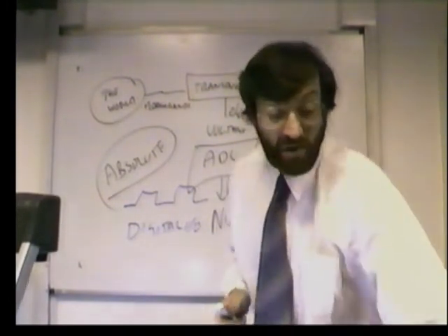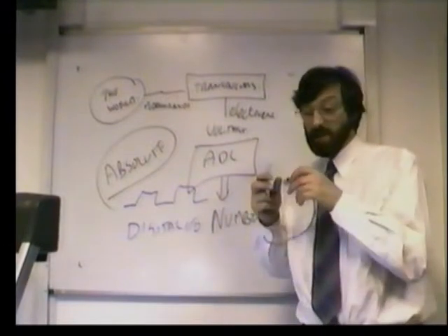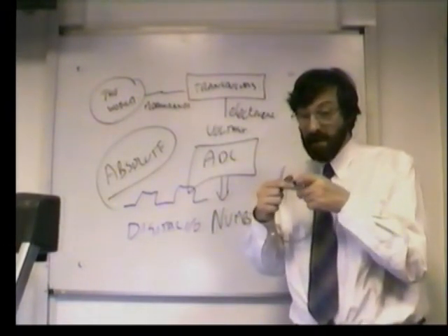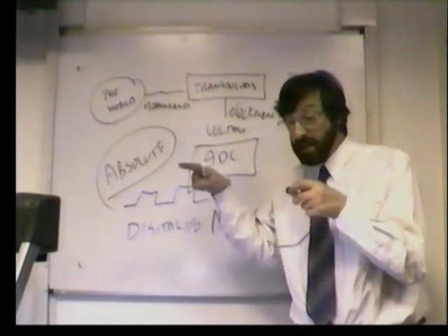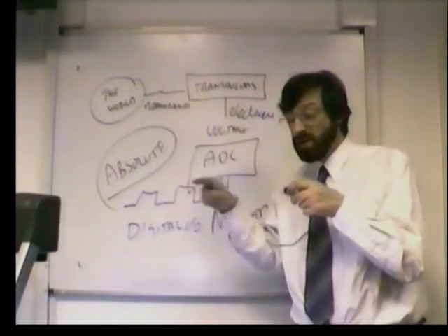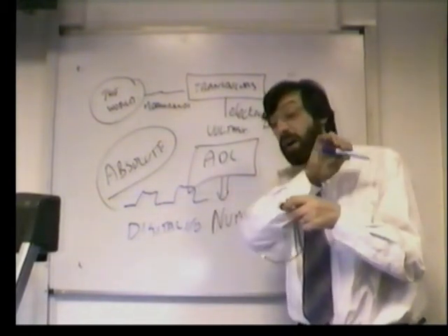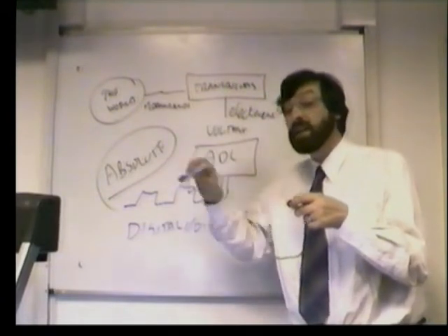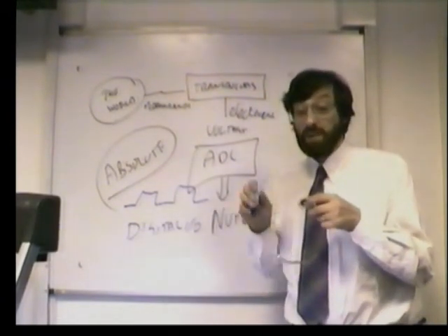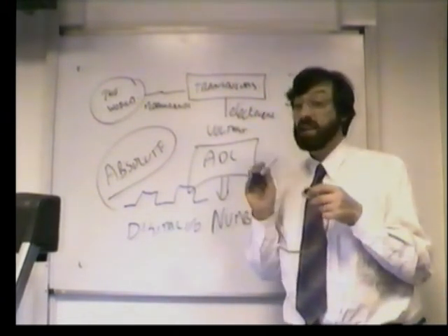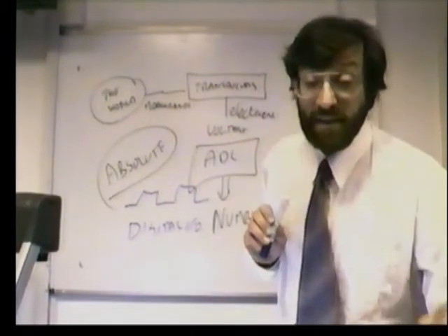So in the case of our turbine meter, here we have our turbine meter that rotated around and around. We could have just counted the pulses to give us volume, but if we time them as well, we know the flow rate. And we're going to use that phenomena to control our very complex electric shower later on in this series.